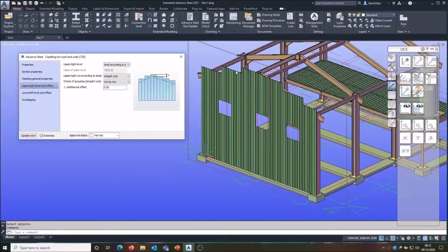You can do that as 1 sheet at a time, or 2 sheets at a time, 3 sheets, or even 4 sheets at a time. So there you go, that's 3 sheets at a time. Go back to 1 by 1. But if you want it exact, then you change that to cut along the slope on that option. And now it's cutting perfectly to my outline.